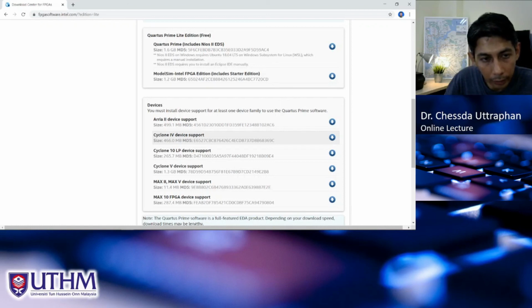I'm not very sure whether we have Cyclone 4 or not. Later I will check, but I suggest you download Cyclone 4 for the device. Don't download all, because the size is very big, especially Cyclone 5, 1.3 GB. So Cyclone 4 should be okay for learning.